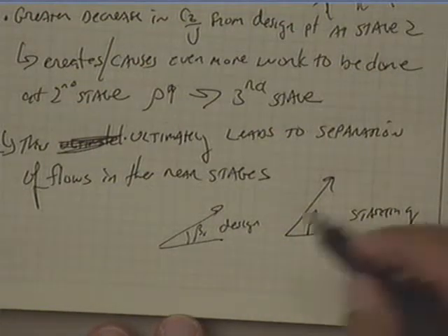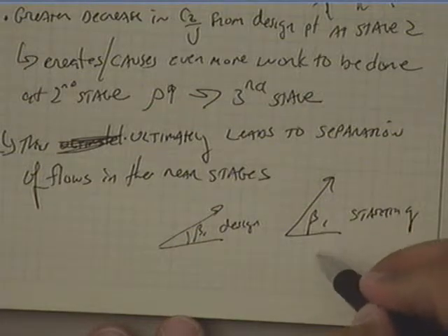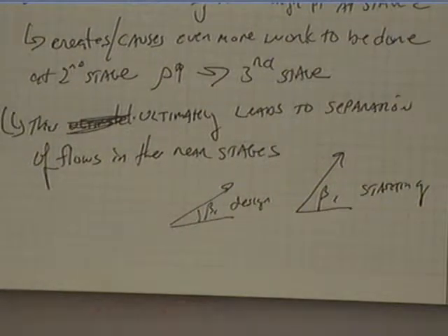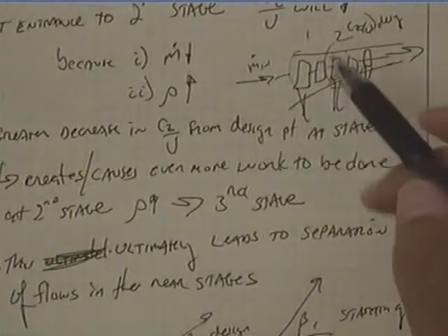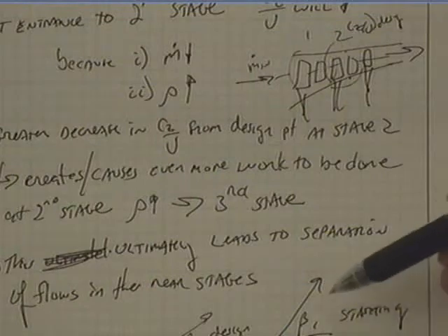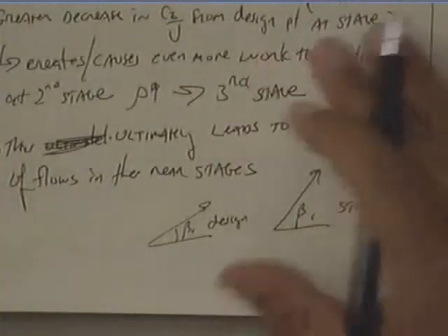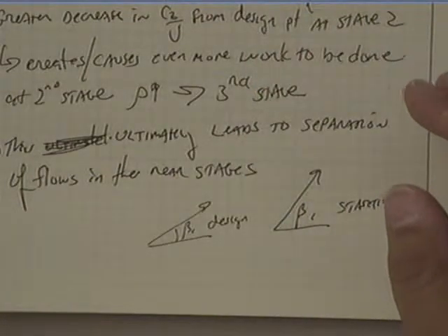What that translates into is that if you recall our definition for incidence angle, I'm going to have a larger incidence angle. So think about this as having a larger angle of attack, and indeed I could be in that region where I could actually stall. Okay, the opposite for a moderate increase in inlet mass flow. You would just get a negative incidence angle or a negative angle of attack leading to a stall in that condition.